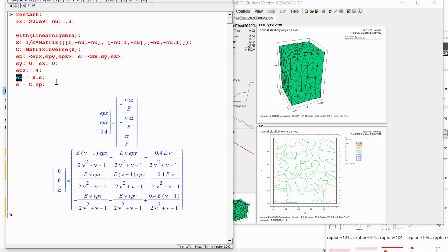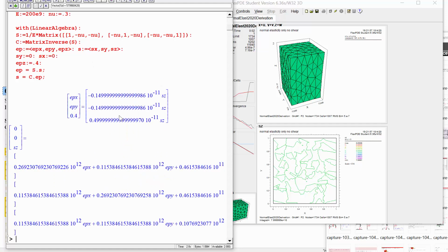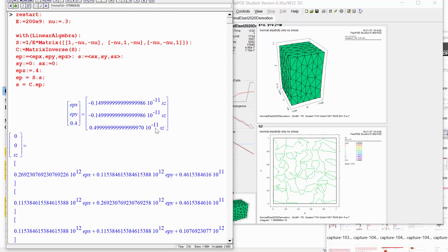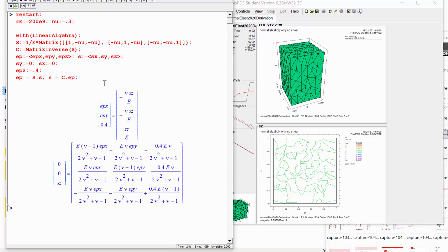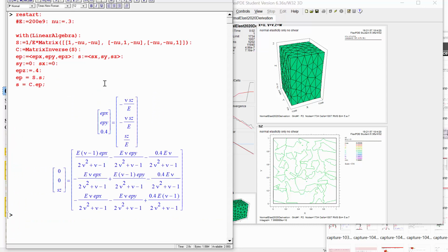Okay, so that means in this particular case, we're going to have 200 gigapascals as the Young's modulus, so that's sort of a bit rough to see, but we could solve the third component of this equals the third component of that. I mean, you could just left multiply it, just like multiply it out and say, all right, well then SZ is equal to 40% of 200, and that's equal to just 80 gigapascals. All right, and that's what we got there.